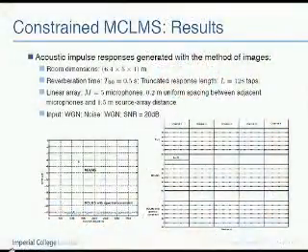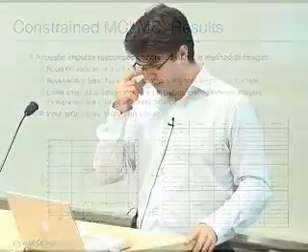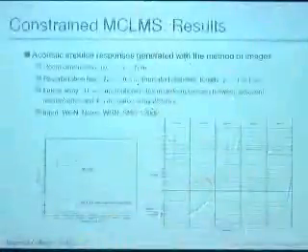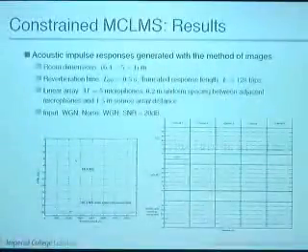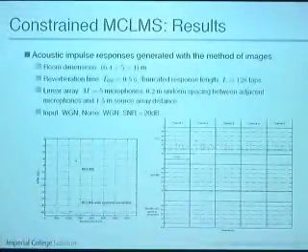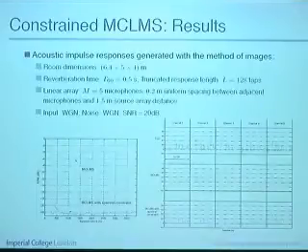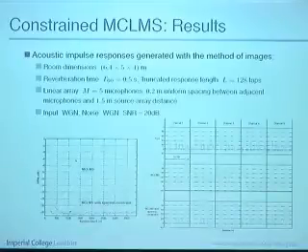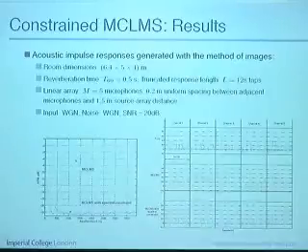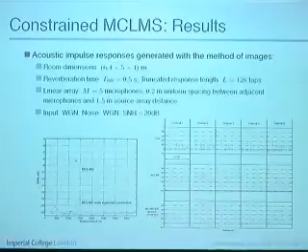And here's just one example of, again, quite short, shortened room impulse responses, simulated as such. There are 5 channels, so each bit here represents one channel of the true ones. The room impulse responses are just truncated to 128 taps. Here is the misconverged solution. What's the sampling rate? The sampling rate is 8 kilohertz here. So it's quite heavily truncated. It's mainly the initial parts of the impulse response.